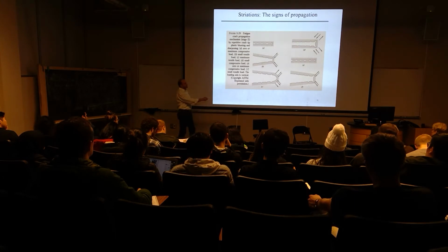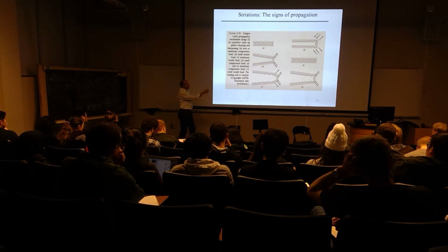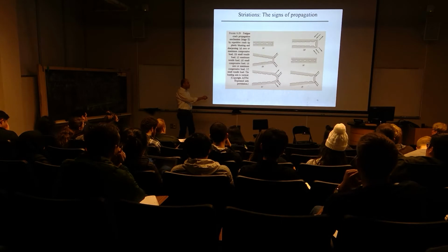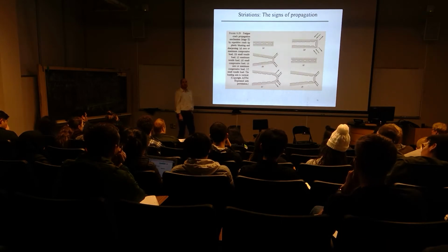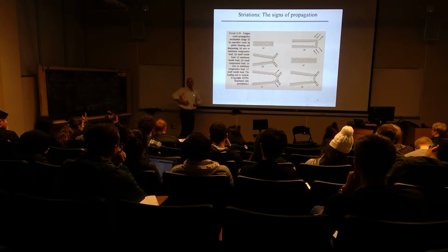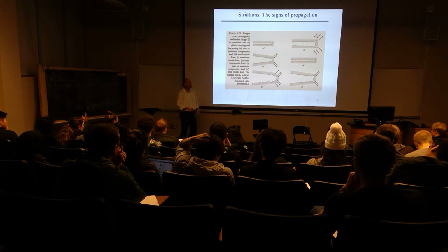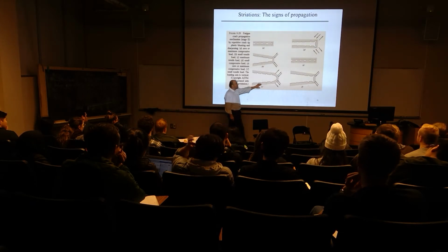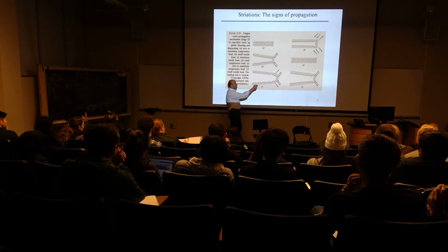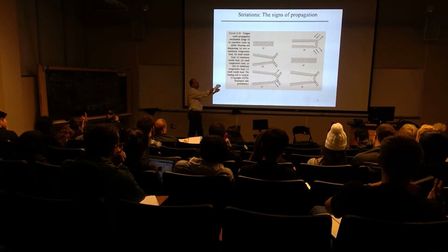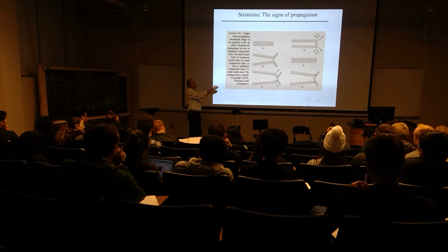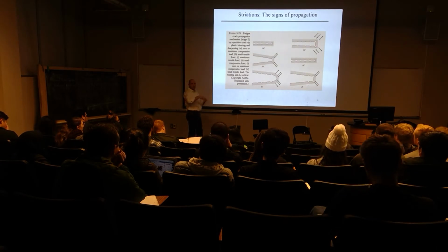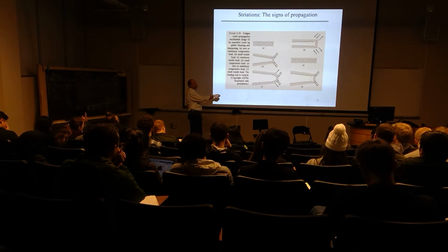So then what happens is that deformation from here to here caused an increase in the surface area of the interior of that crack. So now it's like a sweatshirt that got stretched out because I had a big belly. And then when I lose it, my sweatshirt didn't change, and so it just hangs there as an extra amount of material. And the same thing happens to this crack near that surface. As the crack begins to close, that means as the loading undergoes the reversal, you'll see that marking of that intense increase in surface area is left on that surface.